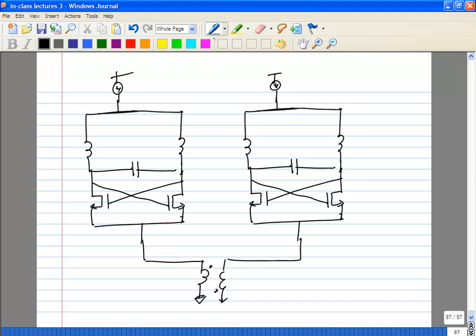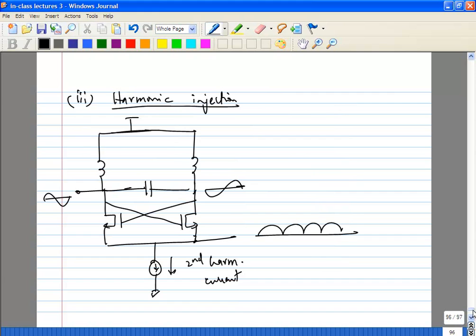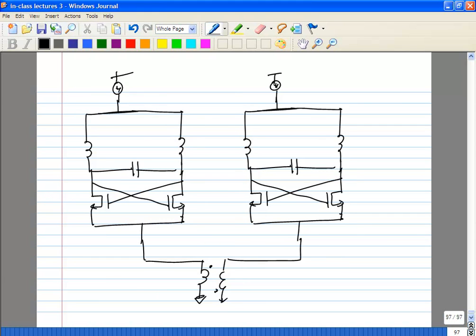Okay, so let's stop here. I think we have pretty much exhausted everything. And of course, I may have forgotten to mention, since you have a second harmonic at the common source node, you can couple to the current source itself instead of going through a transformer. You can take the voltages at this point and feed them to the current sources, cross coupled. There are many ways to do it. Okay, so let's stop here and we'll continue on Wednesday. And I definitely promise phase noise.